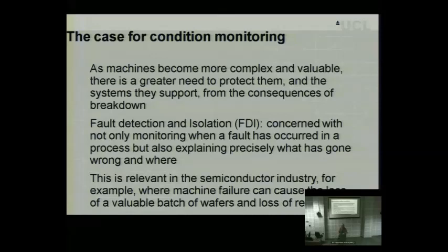So not that there's anything that's catastrophic happened, but there is something different in the way a pump is running, to flag it so that at the end of that batch that it's processing, that pump can be taken out, another pump put in, before it starts the next batch. So it's that indicator of very tiny things that may or may not be happening to give you that heads up. So it's using that equivalent injection, just as we talked about, to see a change.